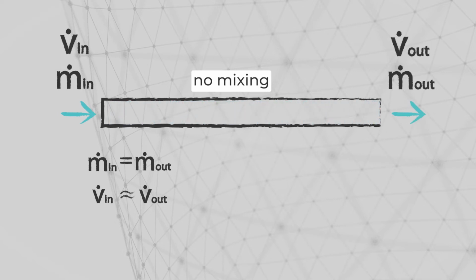You are right to think that in reality, this will never be the case. You will have wall friction, meaning that even in an ideal laminar flow, you have a speed distribution along the diameter of the tube, and therefore your package will not stay together. Nonetheless, the consideration of plug flow is an important concept for continuous manufacturing, and you will hear wording like "close to plug flow" very often in this field.